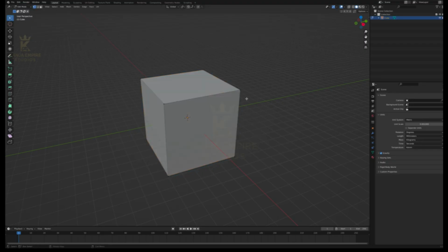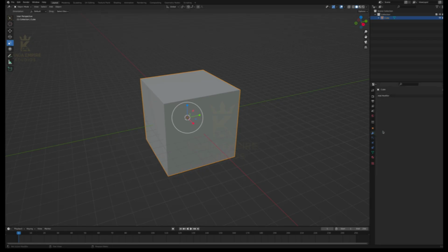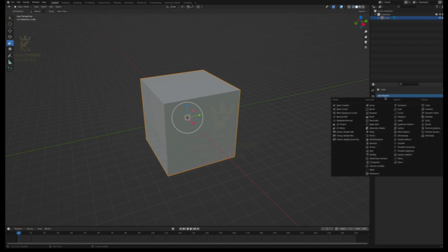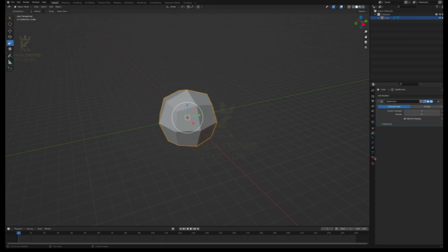So I'm gonna introduce you to a thing called sculpting. Basically it works exactly like how sculpting works in real life, except we'll be sculpting inside of the computer. We'll need a lot more vertices though in order to sculpt our object. So let's go back into object mode, and we'll need to add what's called a subdivision surface modifier. We'll go over here to the modifiers, the blue wrench, and go to subdivision surface. Now you'll see it automatically changes the shape.